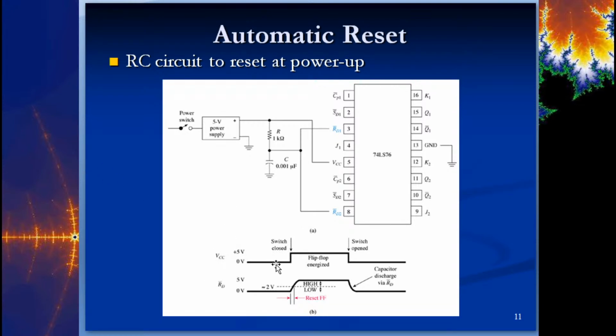So here's the switch closed, and it just immediately turns the voltage on. So you have a spike, right, from 0 to 5 volts. So this thing is at 0, 0, 0, 0, and then it gets turned on and it charges high, and then when you turn it off, right, it's going to discharge that capacitor and go back low. So initially it's going to start out low again because this is connected to ground. It's got somewhere to go.